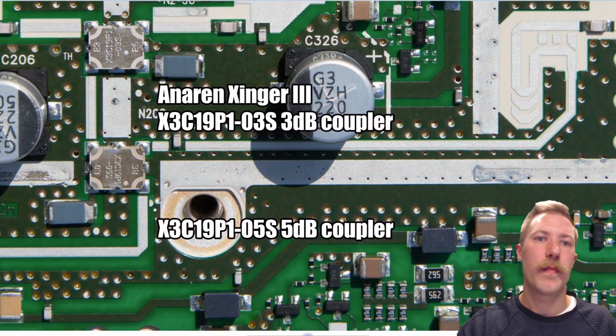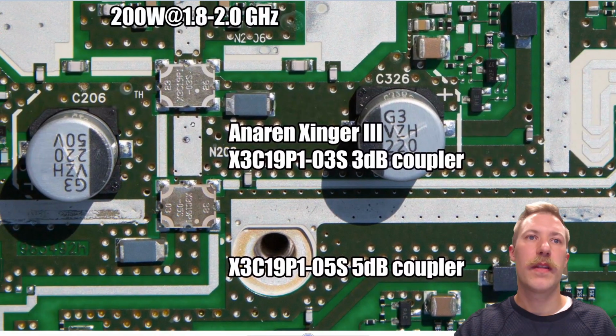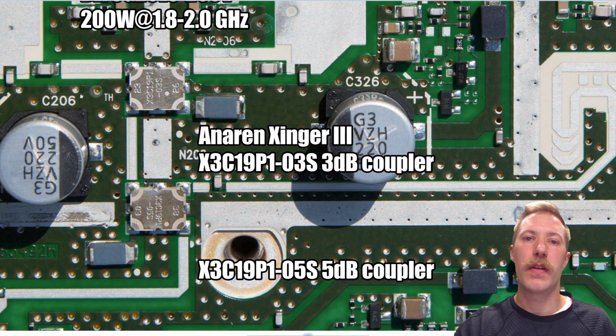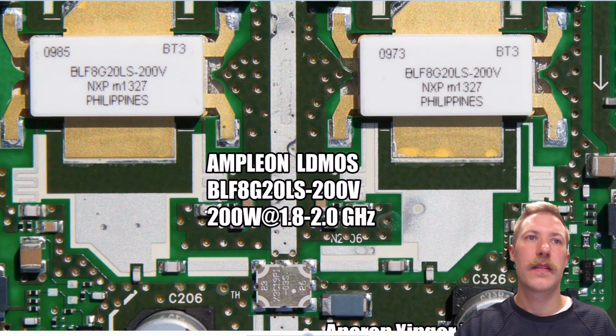signal split up here, where we have 2 Anaren Xinger 3 dB couplers. First we have a 5 dB coupler and a 3 dB coupler. And this is where the signal gets split out into the 3 lanes with the output transistors. And this is where we can see the phase shift over here, and the other one 90 degrees out of phase and a 50 ohm termination. And the same up here, again a 90 degree phase split through the coupler up to the output transistors, which